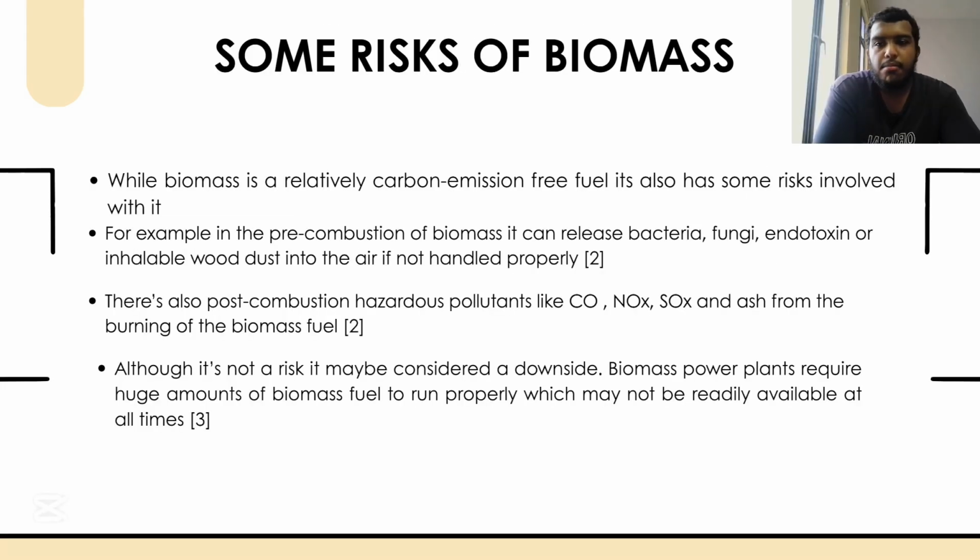Some risks of biomass. While biomass is a relatively carbon emission-free fuel, it also has some risks involved with it. For example, in the pre-combustion of biomass, it can release bacteria, fungi, endotoxin, or inhalable wood dust into the air if not handled properly. There are also post-combustion hazardous pollutants like CO, NOx, SOx, and ash from the burning of the biomass fuel. Although it is not a risk, it may be considered a downside: biomass power plants require huge amounts of fuel to run properly, which may not be readily available at all times.